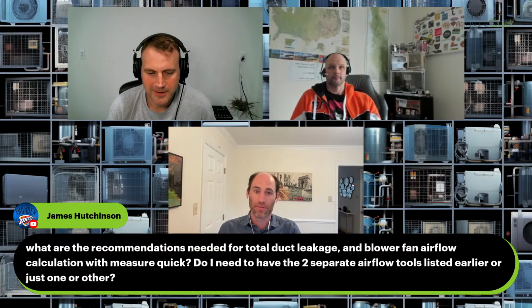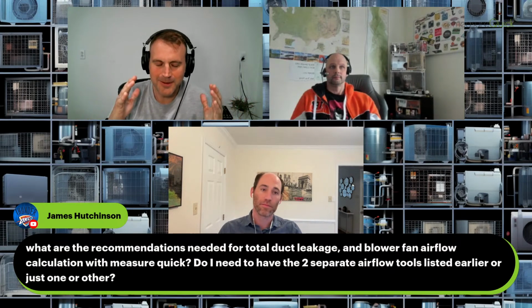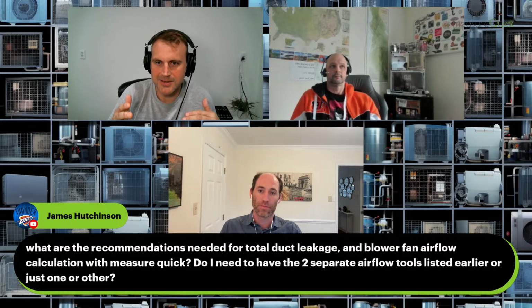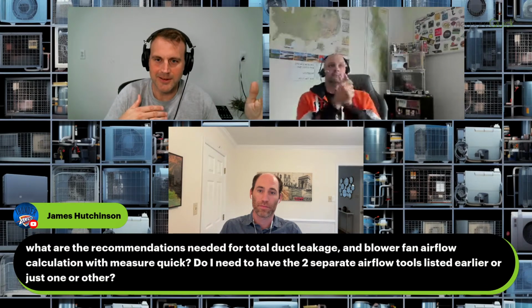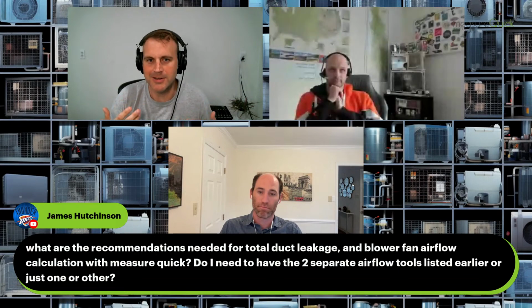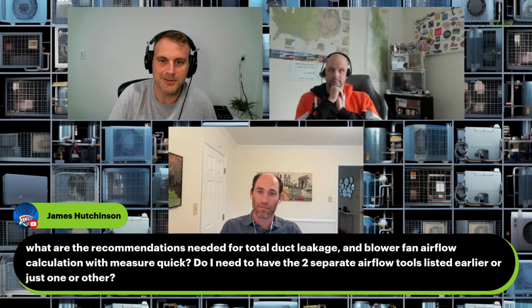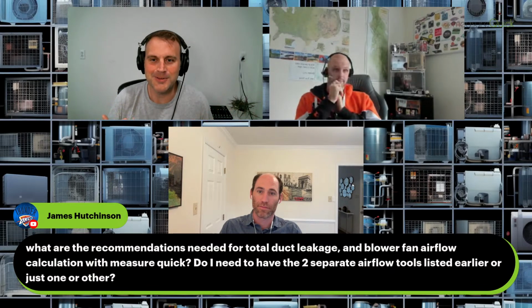So in MeasureQuick, let me see if I answer the question right. Well, let me back up. If you do the standard 310 process, duct leakage is step 2. There's design review, and then there's total duct leakage. And why would you even progress if you have duct leakage? Because if you have duct leakage, you have a problem, and you should address it. Once you address duct leakage, then you move on to total system airflow. If you're testing airflow with tons of duct leakage, why? What's the point? Essentially you have a broken system.